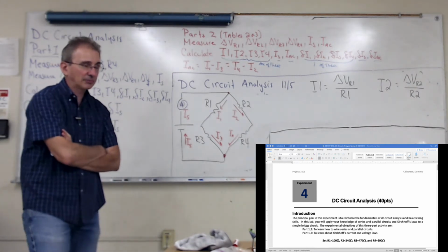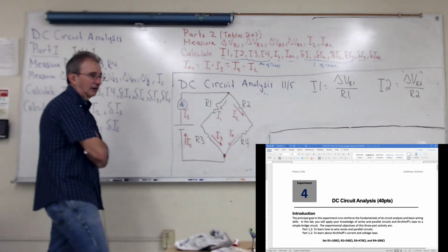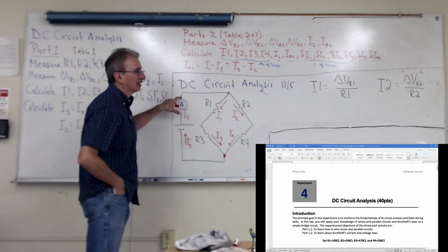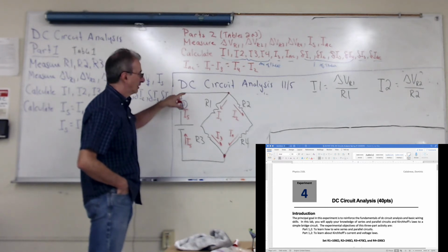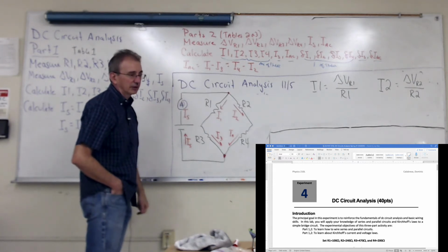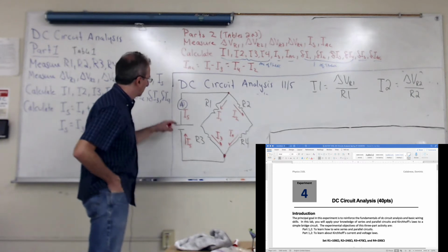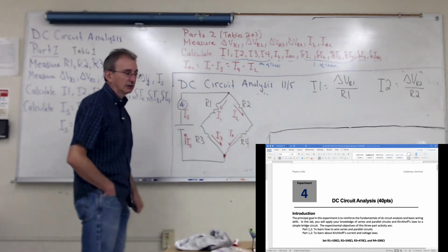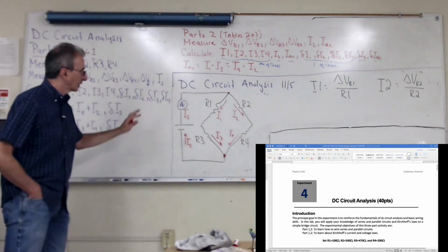And you should also start by, when you're measuring the current, if you want to figure out what is the best scale to use, you can always estimate the total current in your circuit. Or you can just put the ammeter on the highest scale and see what the value is, and then see if you can go to the next lowest scale. Questions on this?